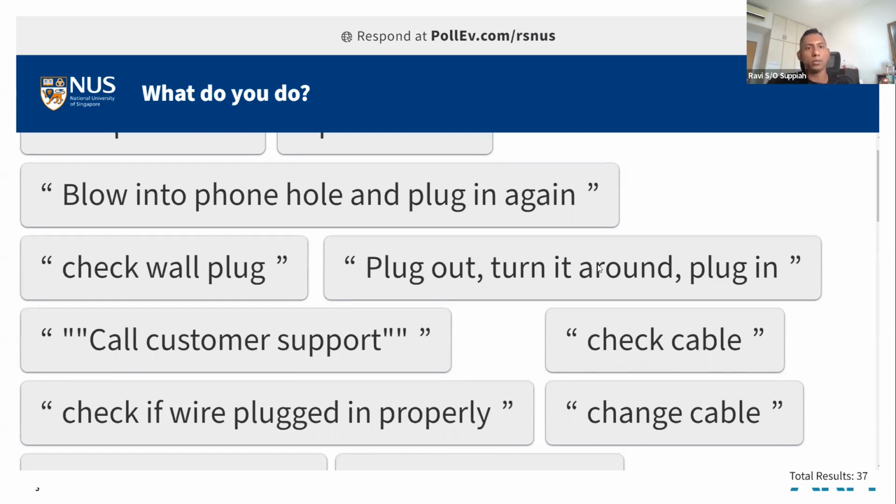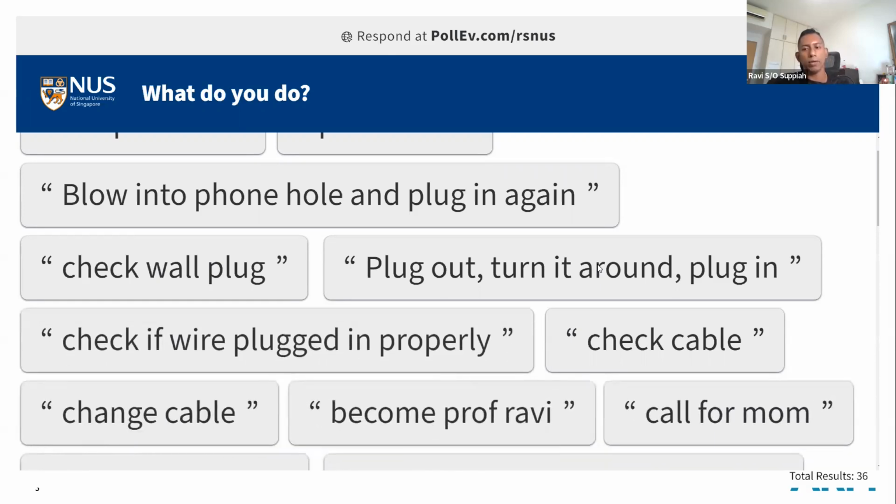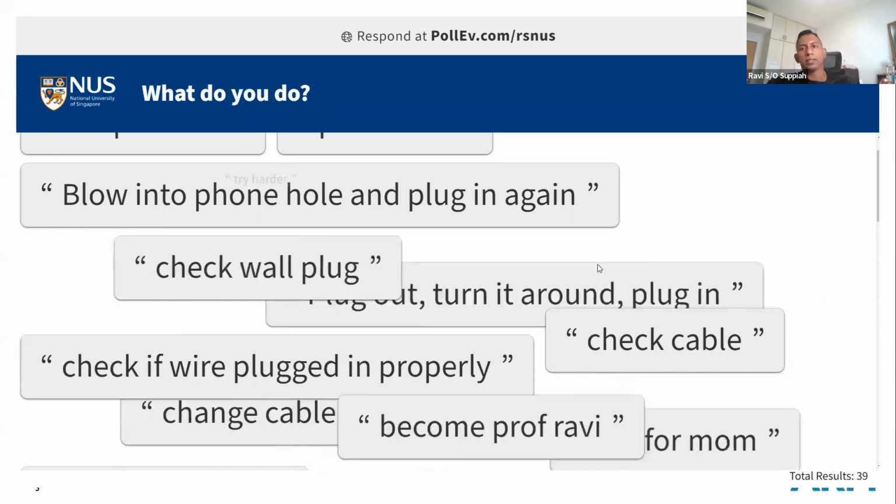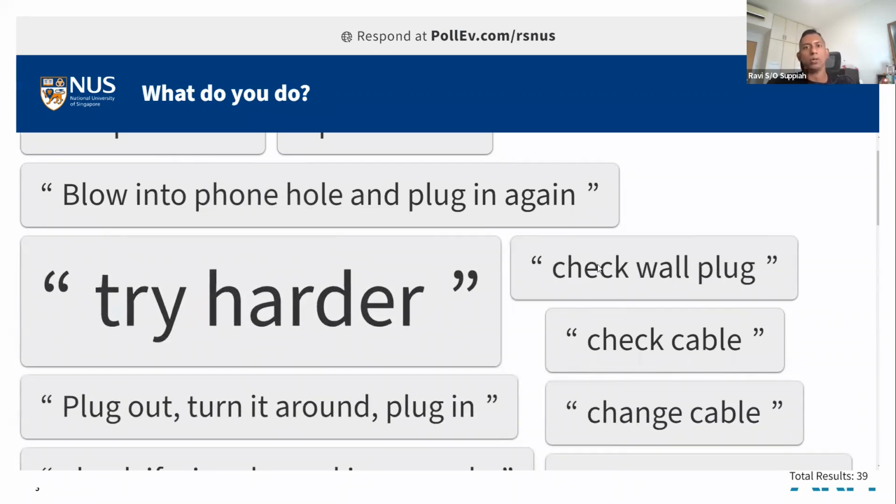You need to figure out what the issue is, so that is where the technique of figuring out step by step what happened comes in. In embedded systems you have hardware and software. Firstly you check the hardware: whether your connections are correct, the wires are correct, the power supply is switched on. If the hardware is confirmed correct, then you look at the software. You try to see whether you configured the registers correctly, or missed out any of the settings. If all seems correct, then you try other troubleshooting: use a multimeter to check the voltage, use the oscilloscope to check the signals and things like that.